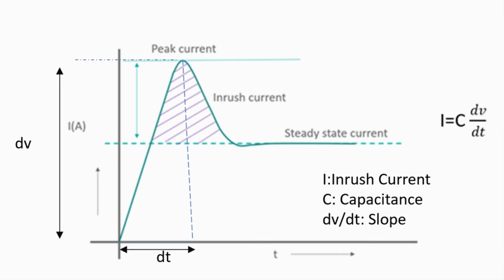Large capacitance value induces high current spikes due to large CdV/dt that can create electromagnetic interference with other circuits or trip a circuit breaker for overcurrent alert. If the current exceeds the maximum rating of components like the MOSFET, or exceeds the inductor saturation current, PCB trace, and other critical components, the system can enter undesired states and the components could be damaged. Portable devices and other battery powered equipment could see a voltage dip from the battery and experience output voltage overshoot during startup transients. Hence, it is required to regulate the inrush current under limits.